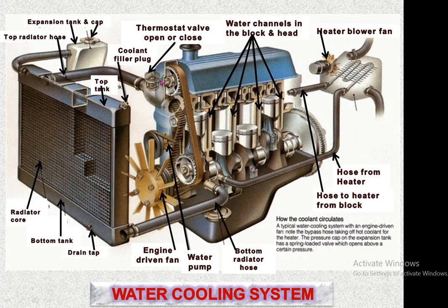Suppose we have set this valve for 170 degree Fahrenheit temperature, then as and when the water that comes out from the cylinder head of the engine reaches 180 degree Fahrenheit, this valve opens and the hot water goes into the radiator.